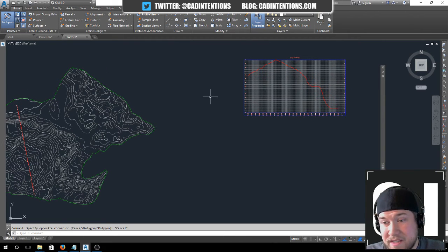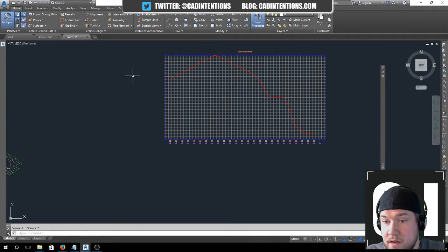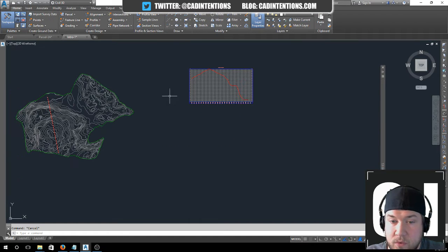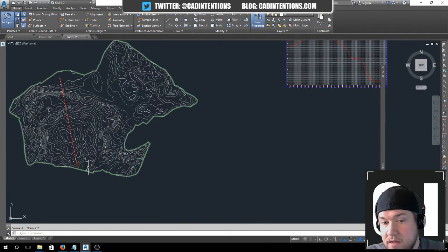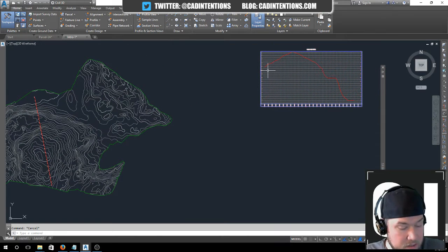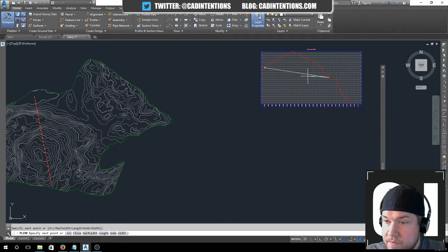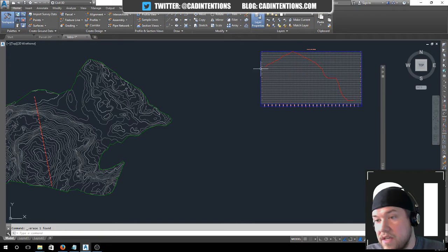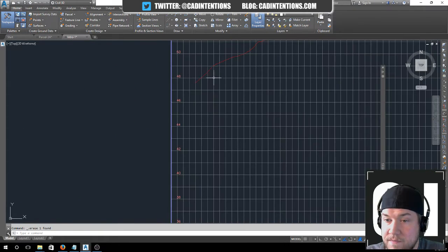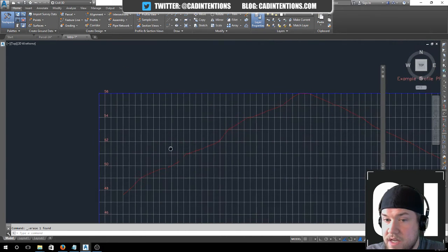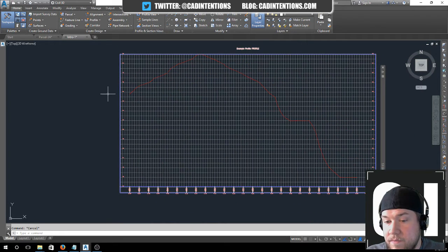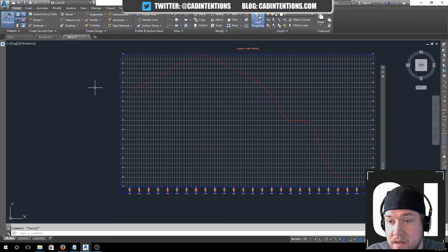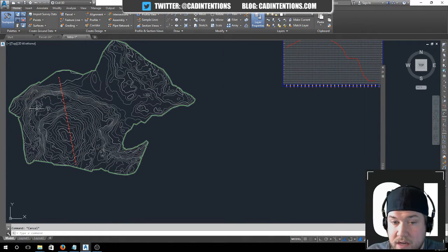That's a quick way to cut a section, or a profile in this case, to give you a feel for what the land is looking like. So you can tell we wouldn't want to, say, design a road that went right through here, because if you wanted to go from here to here, you're going to have to cut or blast through a ton of ground. Even saying this is scale by 10, that's still 48 up to 56. That's still 8 meters of ground, or feet. We're using feet, but that's a lot of ground. You don't want to cut a road across that.